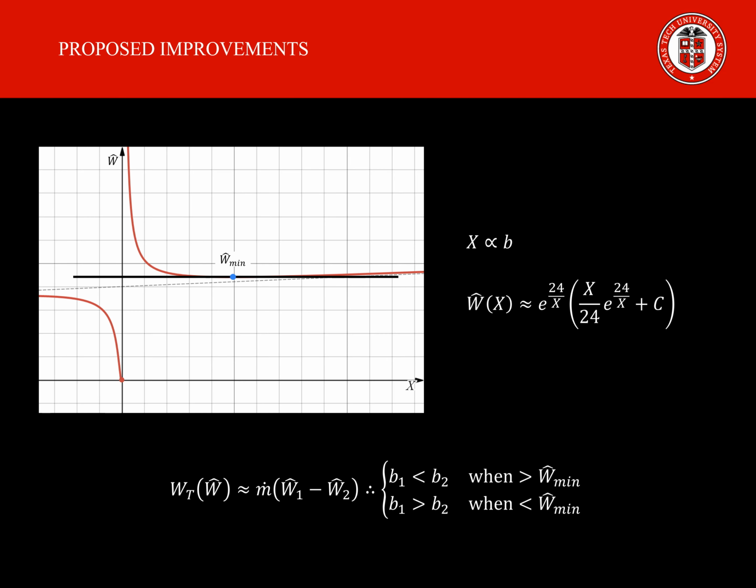I graphed the general correlation that disk spacing has on relative inlet velocity. An inverse relationship comes to light with asymptotic behaviors approaching infinity as disks get increasingly further apart. Turbine output is a subtractive function of relative velocities at inlet and central orifice, and relative velocity is an embedded function within output that is dependent on disk spacing.